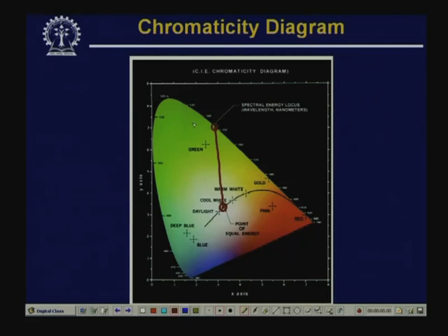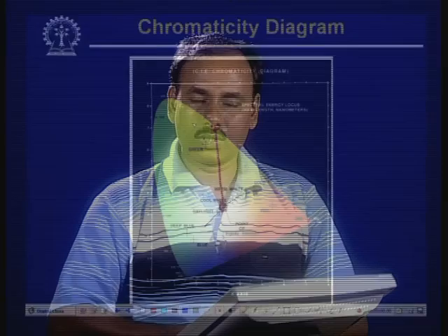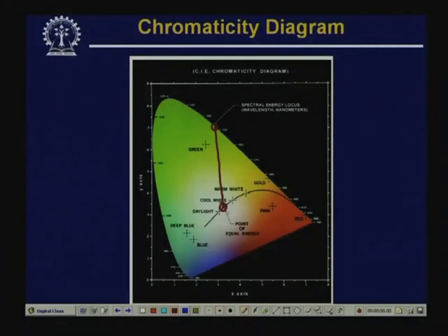As we have said, as we mix white light, the saturation goes on decreasing, that is, we can generate different shades of any particular color. So this straight line, which connects the point of equal energy, the CIE standard of white, and a color on the boundary, which is a fully saturated color, gives us all the shades of this particular color, and they lie on this straight line which joins the boundary point to the point of equal energy.